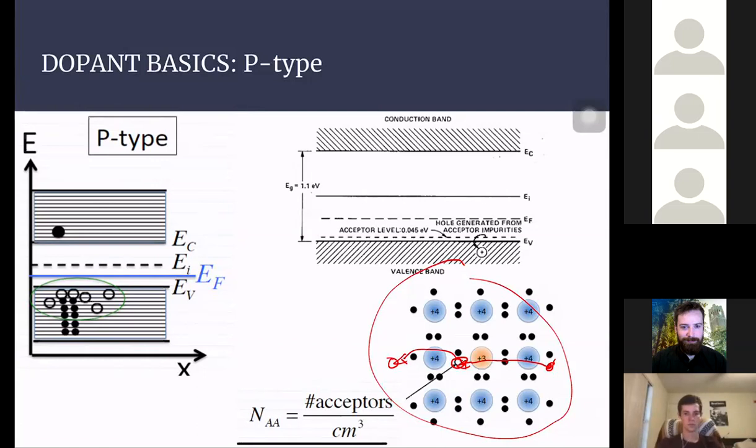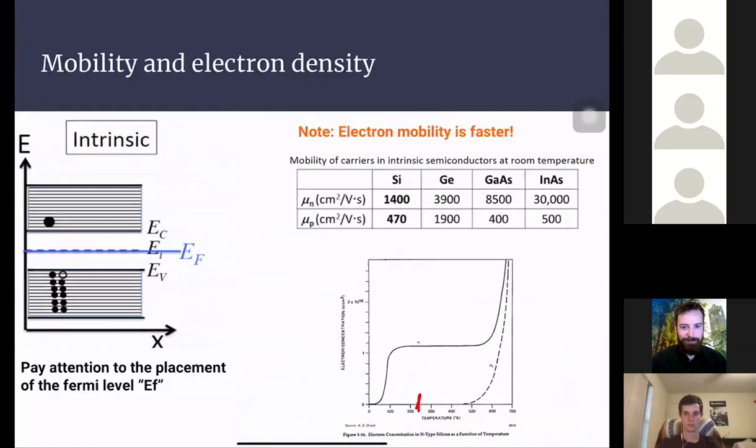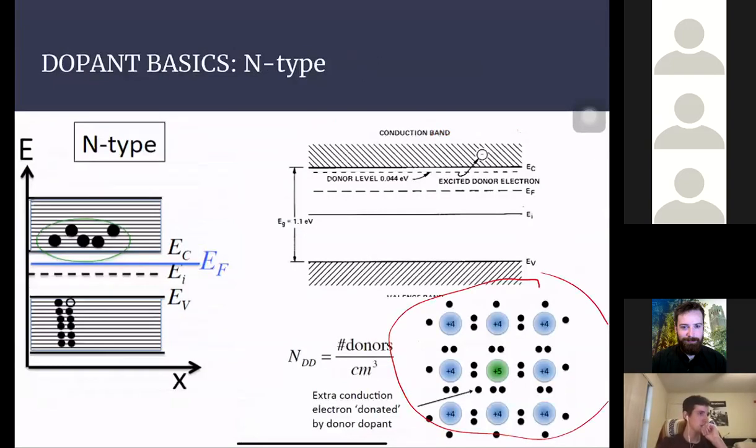Now, depending on these things, the Fermi level, which I mentioned previously, changes. In a normal intrinsic semiconductor, the Fermi level is in the middle of the band gap. But as we add N-type dopants, there are more donors, meaning more electrons are present towards the conduction band. That means the Fermi level shifts towards the top. The Fermi level, as I told you, is a place where you can find an electron easily, like 50% probability, but that's all statistics. We don't need it here.